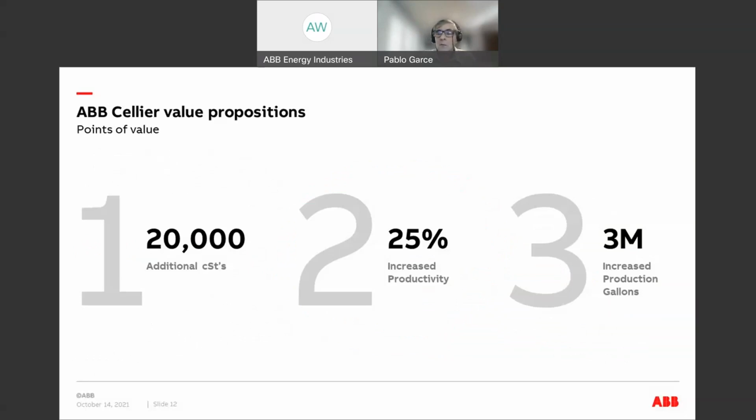So at the beginning, we were talking about the 20,000 centistokes. In a typical drum decanter, if you tilt a drum by hand or you put in a hose, it will top off more or less at 1,500 centistokes. So, in order of magnitude, 10 times less viscosity can be decanted. Otherwise, you have to put it in the oven because it doesn't flow. The drum decanter that we're talking about can decant 20,000 centistokes, and it can do it in 9 minutes. That's the characteristic that we were talking about.